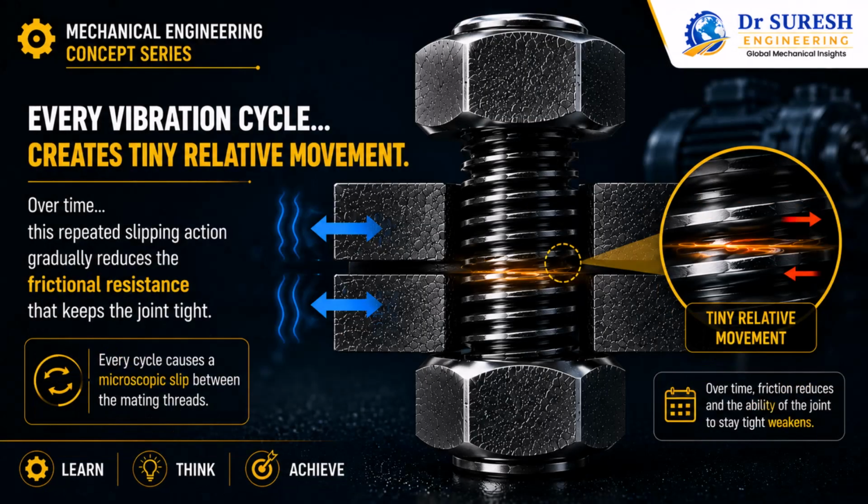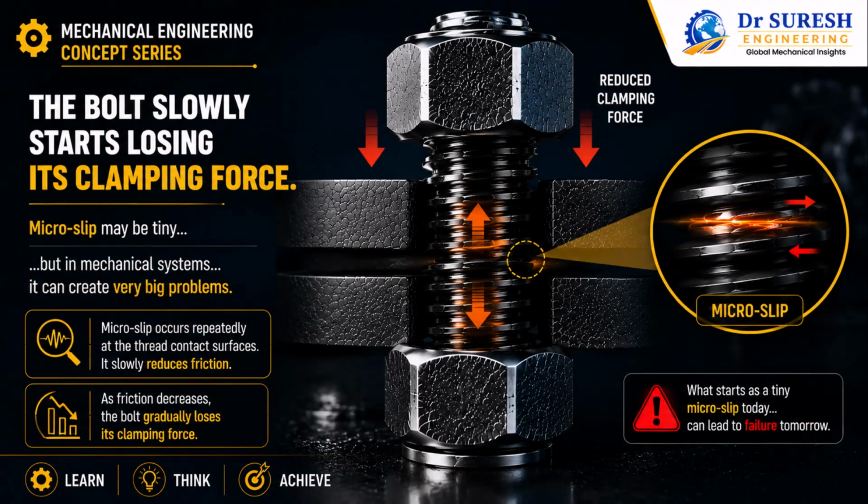Every vibration cycle creates a tiny relative movement between the mating threads. Over time, this repeated slipping action gradually reduces the frictional resistance that keeps the joint tight, and once friction begins to decrease, the bolt slowly starts losing its clamping force. Microslip may be tiny, but in mechanical systems, it can create very big problems.